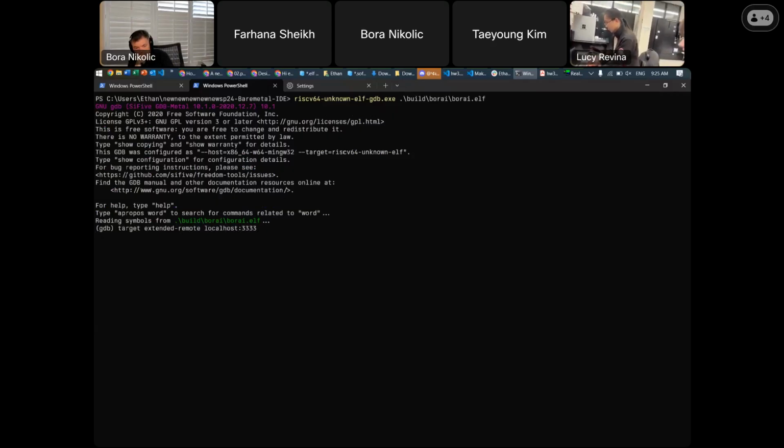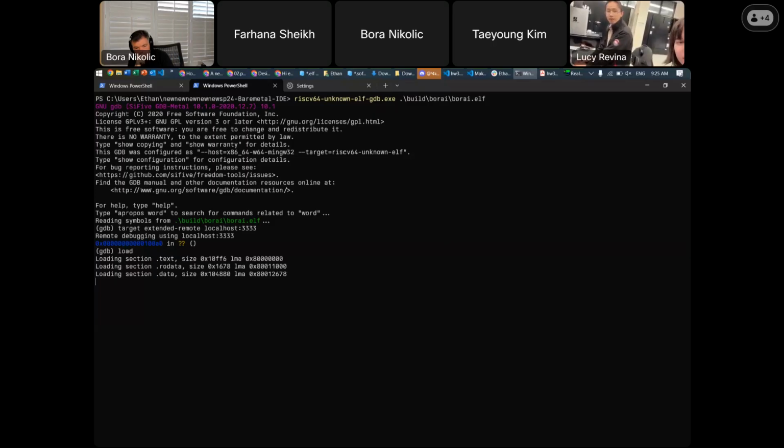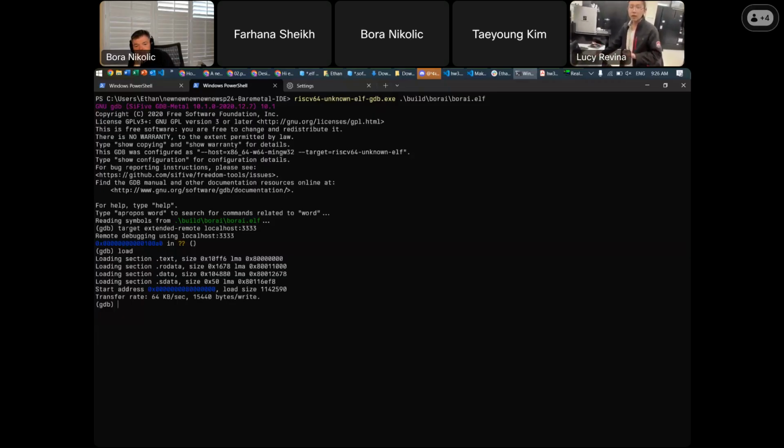And we've been talking a little quickly, I realized, but yeah, you can see on screen right now the setup for the Llama demo. So what we're doing right now is we're just loading in the compiled Llama binary, and all this does is it configures the PLL to take the 50 megahertz it's getting from the actual board and bumps it up to 500 megahertz and starts inferencing.